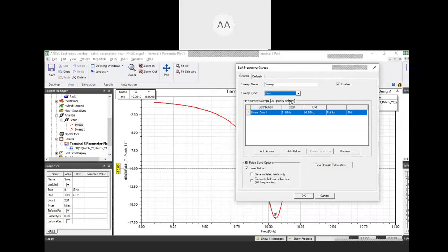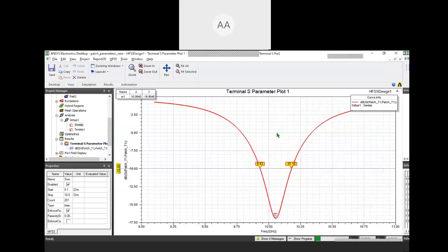This is one disadvantage. Hence, what we do is interpolating, we calculate everything out here, and then we run a discrete sweep. It is not a disadvantage, it is kind of an optimization to run the interpolating at our required frequencies, and then whatever frequencies we are interested in, those frequencies we extract and run the discrete sweep. So it is running. In the meanwhile, let's see other results.